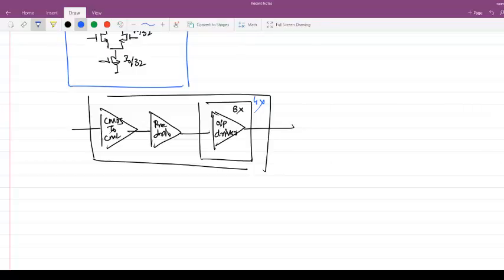But if I keep everything uniformly segmented, it still adds an overhead. Whenever any cursor tap comes in, I need to spend 4 for that. So we do not do that. What we can do is use a mux here. Each cell can have a mux having dn and dn minus 1, and a select signal which makes the branch select between dn and dn minus 1, because the maximum output swing is fixed.